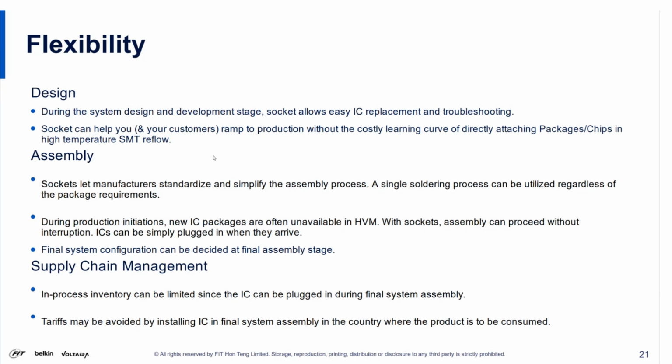Okay. Assembly. Sockets let manufacturers standardize and simplify the assembly process. A single soldering process can be utilized regardless of package requirements. So oftentimes you can reflow all of your board side connectors on at the same time. Sometimes IC devices require specialized or customized SMT processes, which could lead to defects. You take that IC SMT out of the equation when you're socketing.